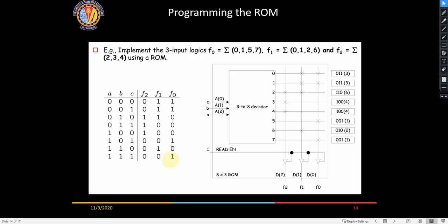Yes, I'll come back to EEPROM once I finish this slide. So these are the 3 functions which we have written here. Now when we activate these minterms, one of these lines will go active. So how to take out the functions? By programming the particular lines of the PROM, using one of the techniques we discussed earlier, by making the connections at the required place.